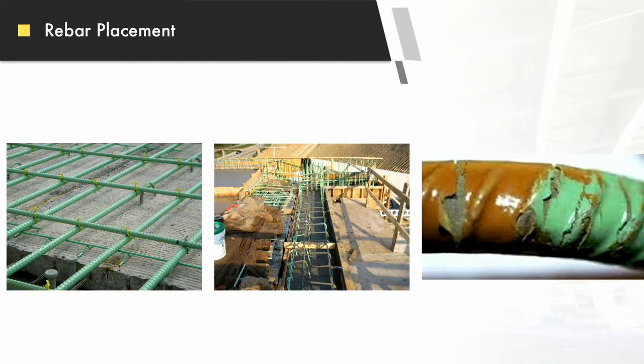This picture here in the center is an abutment diaphragm, and you can see that they didn't chair off their rebar here on this form, because as they placed it, everything's shifted, and now you're burning form right there on that side.